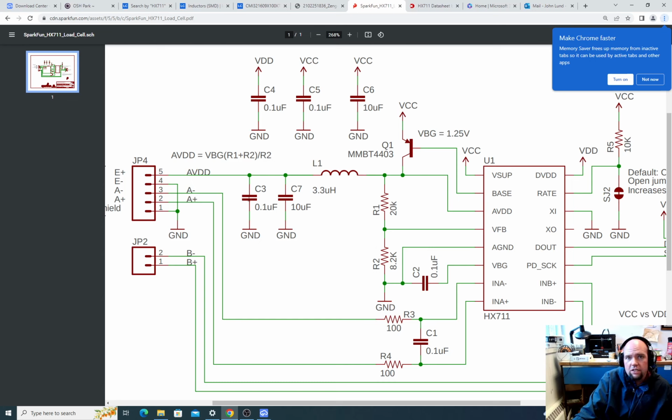The reason they put a small capacitor in a big one is because the dirty secret with capacitors is that big capacitors normally have very bad frequency response. That is to say, to a high frequency signal, this 10 microfarad capacitor would not appear to be 10 microfarads. Why is that? Because when you make really big capacitances, the way they do it is they have lots of large planes of metal with a very thin insulator between them.